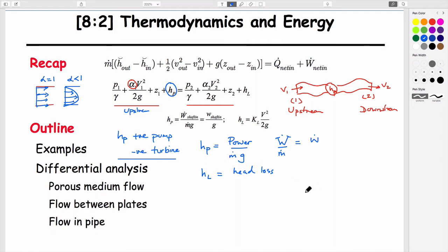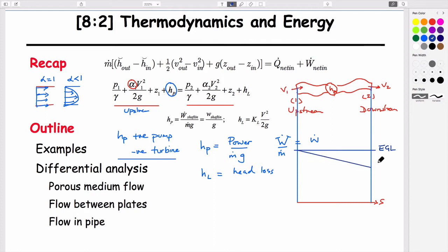And physically, I guess what it might mean is if I come down here and attempt to draw a diagram that relates these, this is along the streamline. What this physically means is that if you take what would be a magnitude which is constant, we often think of this as the energy grade line. All that this physically means is that there's some head loss, which is losing energy as you flow down a pipe because there are these frictional losses.